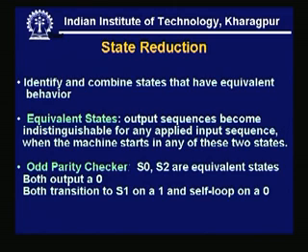So say for the odd parity checker, S0 and S2 are equivalent states because both transition to S1 on a 1 and self loop on a 0. We check.